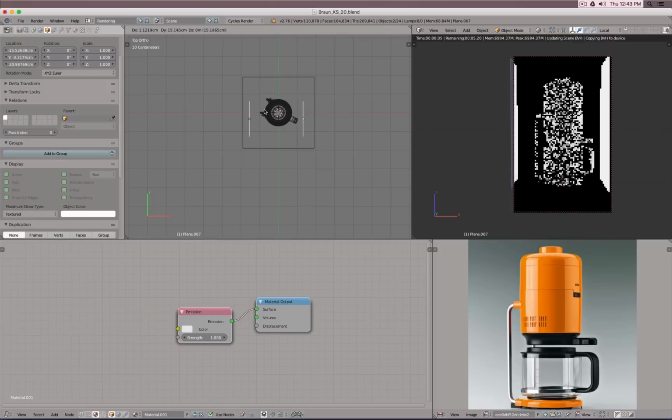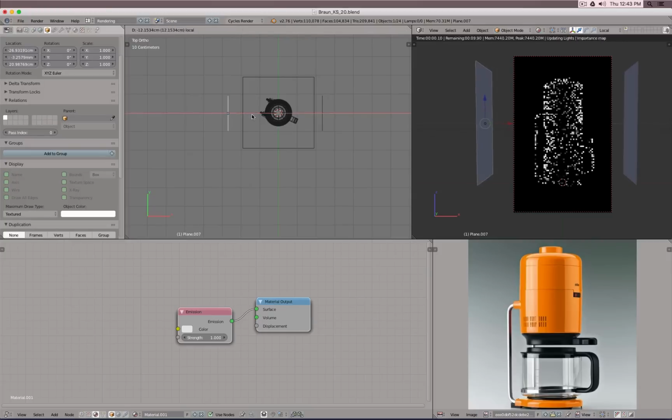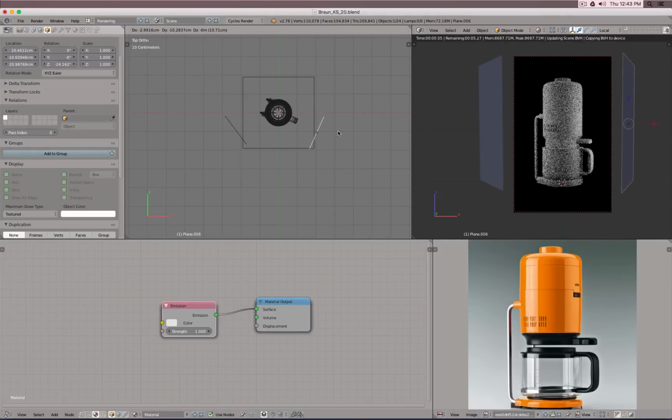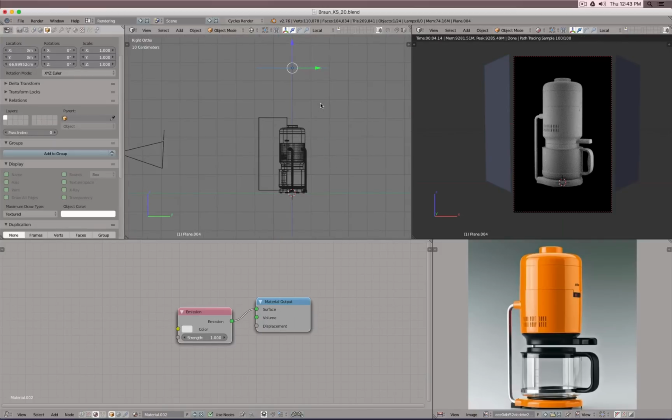So you also see that I do this kind of play around just with a grayscale object. So I have no materials applied, and that's actually not too bad because this teaches you a little bit about how your object might react to different light sources. So without the materials, I can understand already how my lights might actually impact or influence my object. And then I can customize it or adjust it.